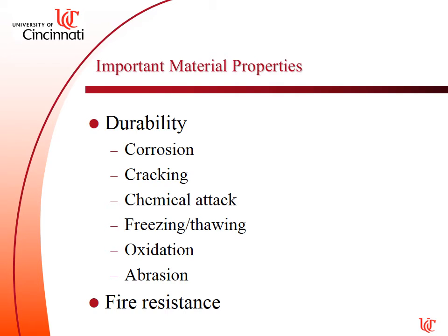You have to think about corrosion. If you're in a corrosive environment, is steel going to work? Is reinforced concrete going to work? Or is something going to work better? What's easier to put coatings on? What's easier to put certain technologies in place that battle corrosion? So we have to think about that.